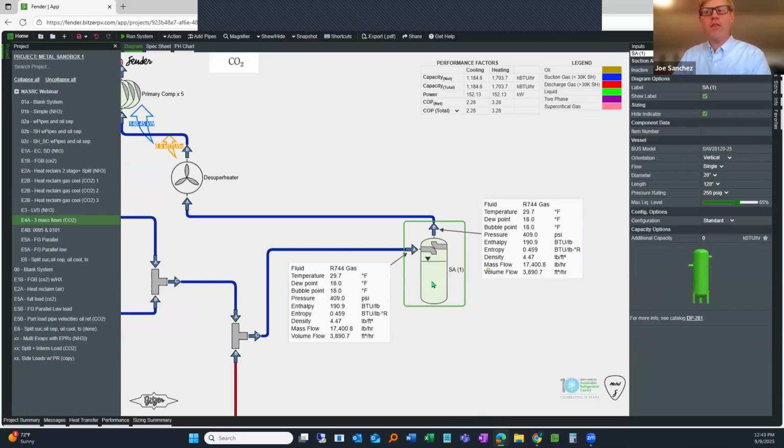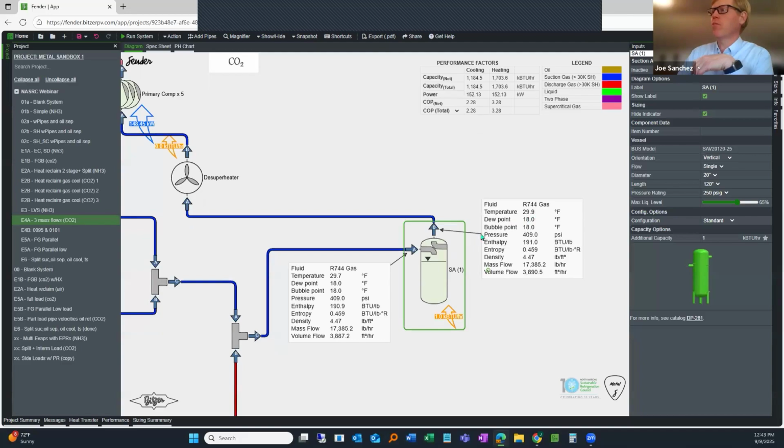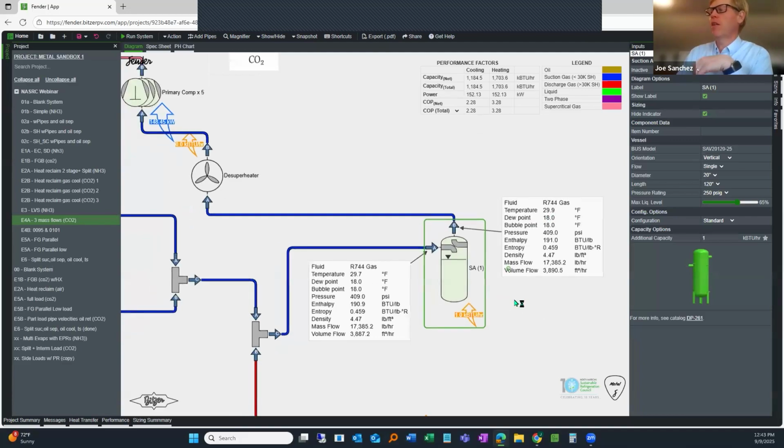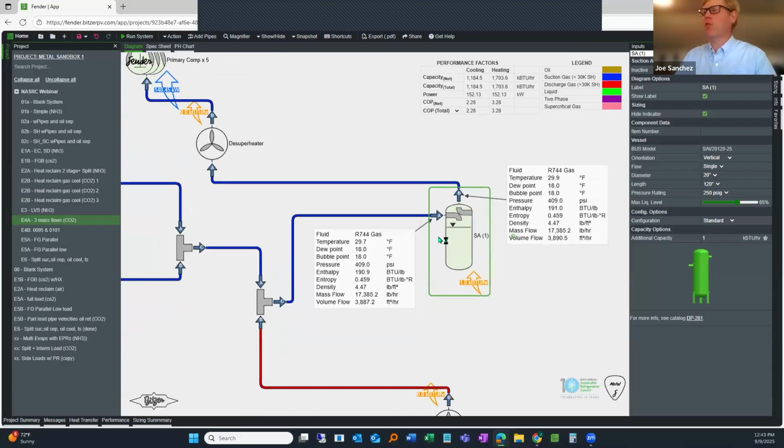And crankcase heaters, I would say just about any heater you plug in is only going to be effective in a standstill situation. So you can see with a system as large as this, if we put 300 watts, which is about 1,000 BTUs per hour, you're only moving the refrigerant like 0.2 degrees. So it's very much only for a static situation. It would never be used in an actual running system.